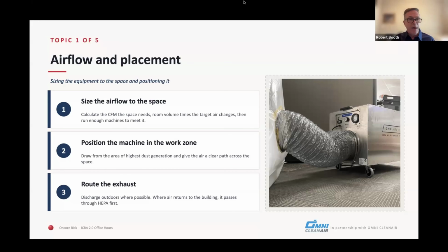We want you to verify that. The way you verify that, we'll talk a little bit more about down the road, a couple of topics later. But you're going to verify that it reduces the particulate at the achievable portion that a HEPA filter would, which is 99.97% at 0.3 microns. And that basically means that we get good filtration through the device.